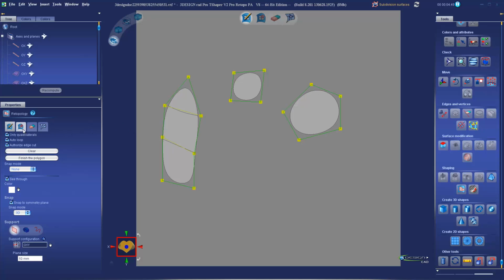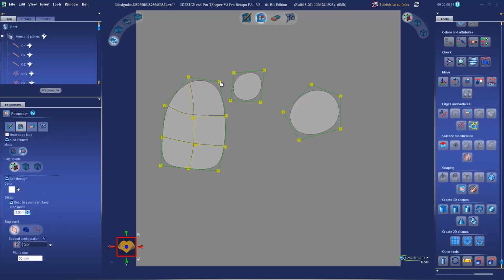Okay. The second tab allows us to move and copy our polygons, which makes it much faster to get our mesh laid out. So instead of having to draw each square individually, we have 2 modes, Move and Duplicate. In Move, we can edit the mesh that we've already started and clean it up as we go. Or we can Duplicate. In Duplicate, if you grab either an edge or a point, you can quickly duplicate out those polygons and fill in your mesh really quick. Anytime you have a corner like this, you don't want to grab the edge because you'll have a split between the two. Instead, grab the corner and pull that out to the other side, and we can finish that up quickly.